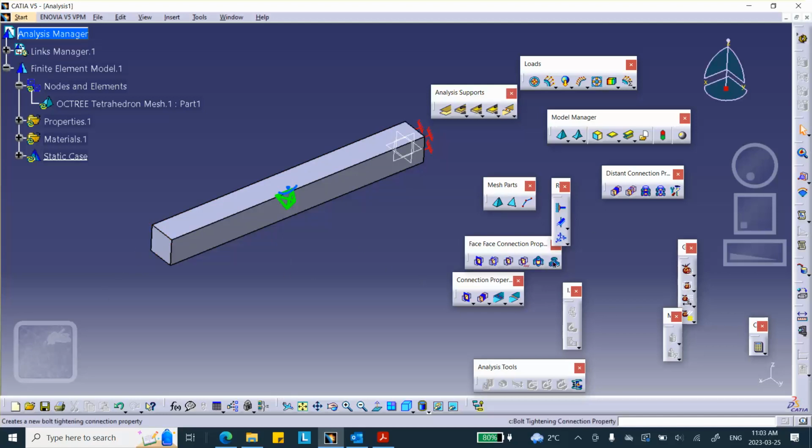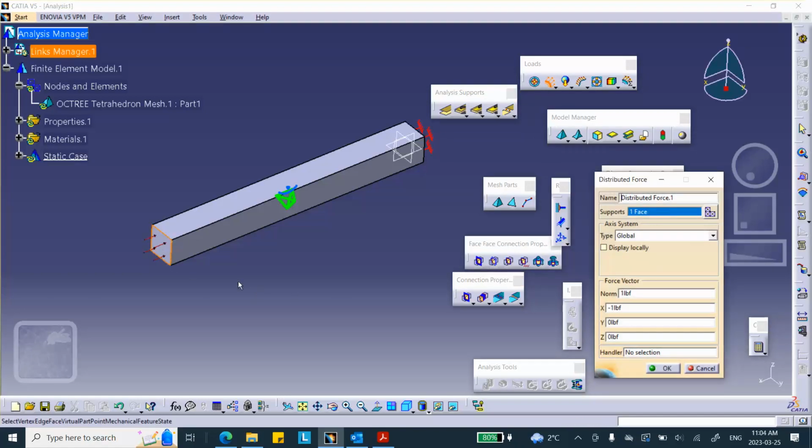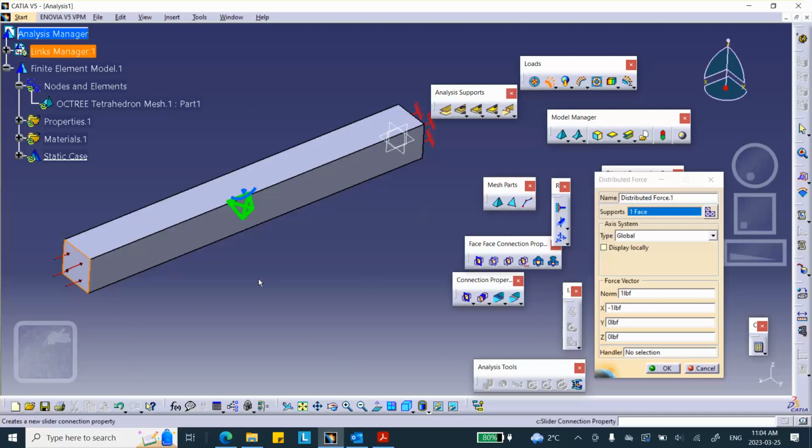So you put a 1 pound dummy load here. So that's going to be a load. Where's that force right there? And 1 pound. Notice that I already have it in the correct direction. So -1 and 1 pound. Now, by the way, if you do a positive one here, and look at the selection tab, all the buckling factors are negative.